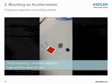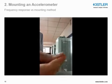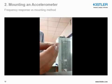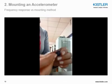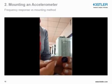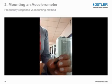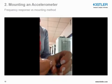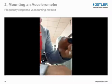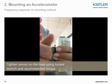In that way, we are using wax again, but this time we are using an isolated mounting base. And once again, we are going to apply 3 small pieces of wax. Screw down the sensor using the torque wrench again.